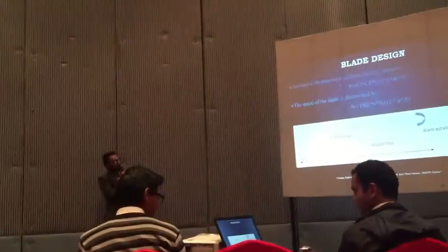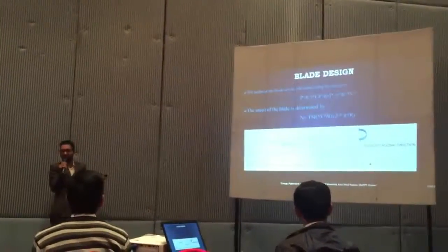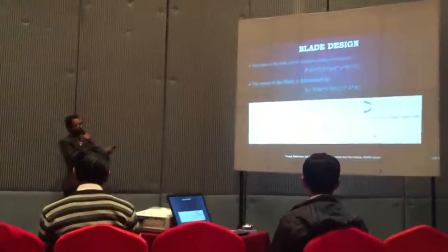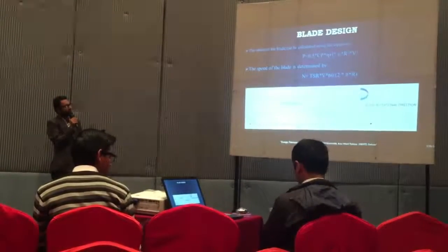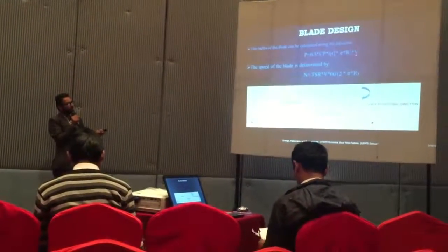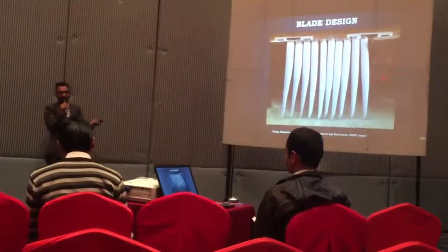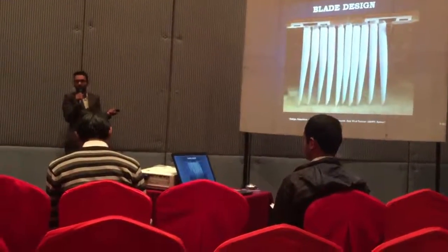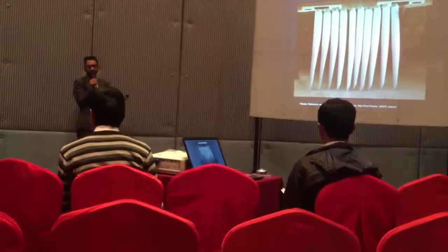Power generally depends upon the cube of the velocity of the wind. Power is directly proportional to R squared times velocity cubed. These are some of the blade designs we have made in our lab. These are for testing. We have tested significantly.